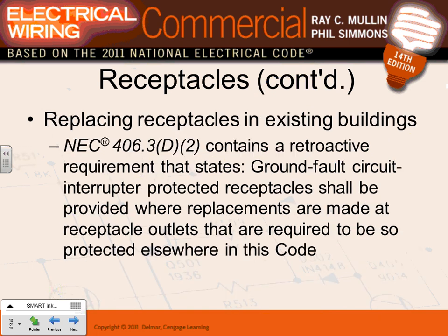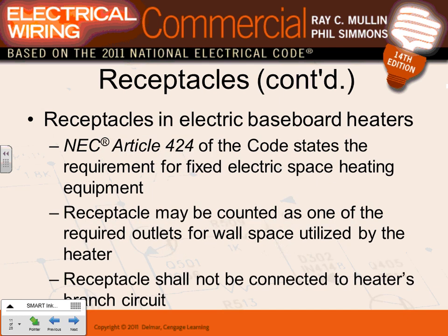Okay, so that's your receptacles. When you change a receptacle, it talks about changing receptacles. You guys are not electricians, but if you walk into a remodel, Andrew, my friend, you want to remodel a building and you have non-GFCI receptacles in a commercial kitchen, you have to change them with what? GFCI. This is typical, guys. You have to change a non-GFCI receptacle with a GFCI receptacle.